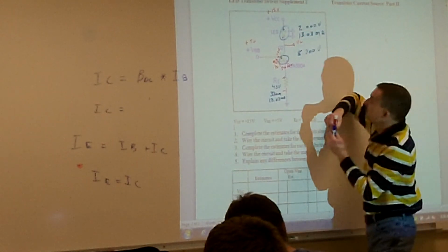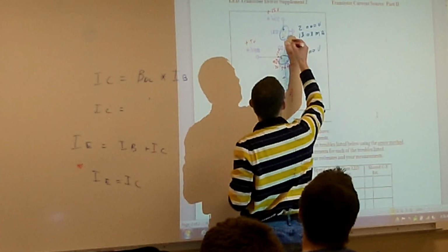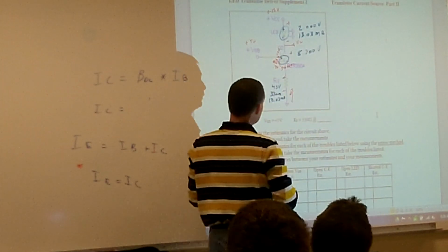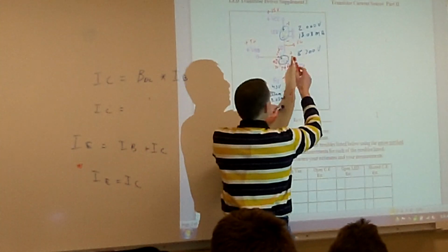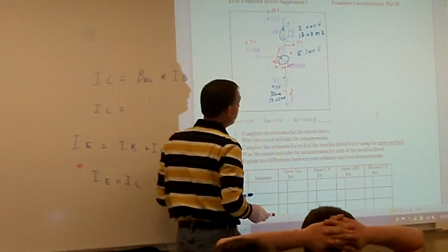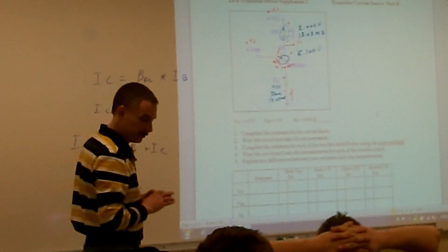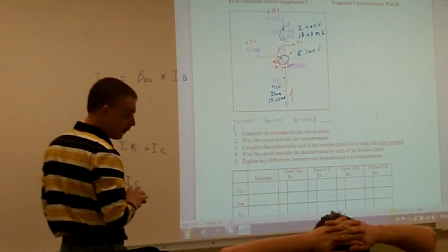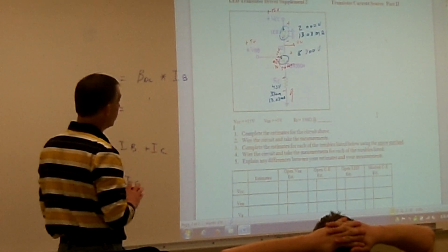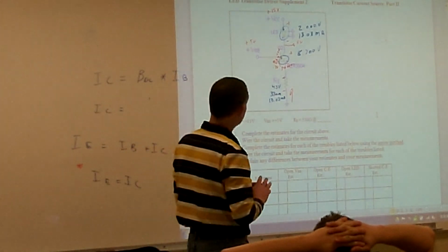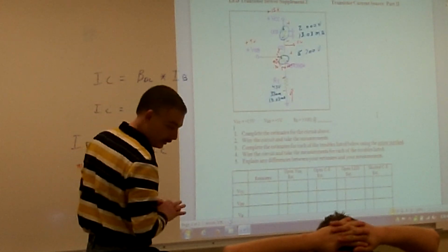Because if we were to actually put in our current paths, we know my current's coming up, negative, positive, negative, positive, negative, positive. So I'm just taking my 8.7 volts that my collector to the emitter is dropping, plus my 4.3 volts, and I get a positive 13 volts going from my voltage of my collector. And we already did determine that the LED is turned on. We have enough current going through it. We have enough voltage across the LED, so the LED is turned on.